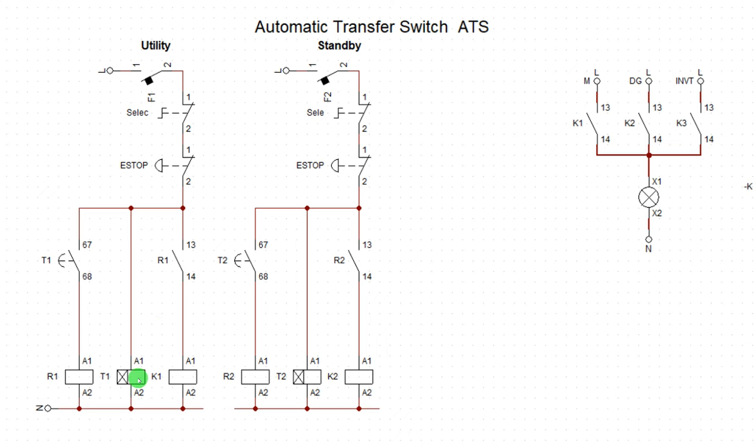Now this one is the first timer in our design, T1. If we introduce another timer, it's going to be T2, and that is T2 here. Now this is the first contactor in the logic. If you introduce a second contactor, it's going to be K2. This is K1 and this is K2. Even in your real life design, that is how you label your contactors and your timers.